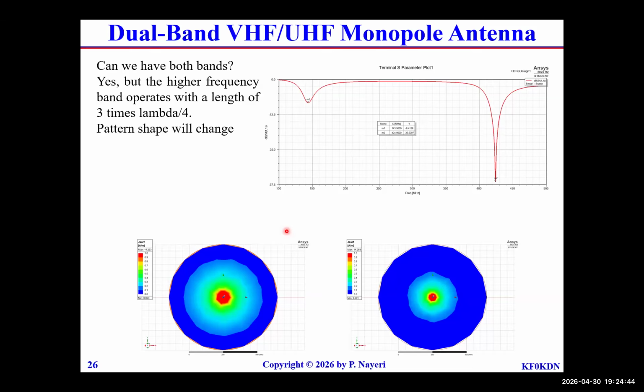you say there's a threshold in terms of your matching. And I trust you've seen this in your 375 lab. Our threshold is minus 10 dB down. If you recall, 10 dB down corresponds to 90% throughput of power. So what we are saying is across this frequency band, 90% of the power gets through.